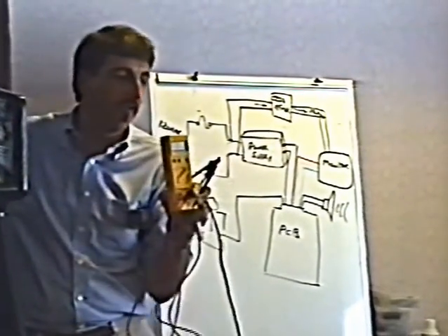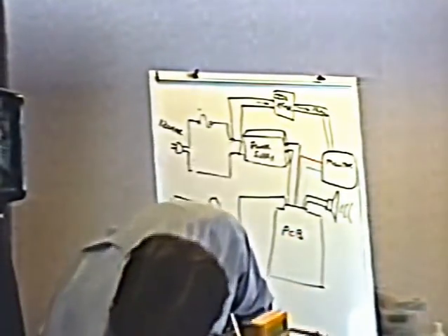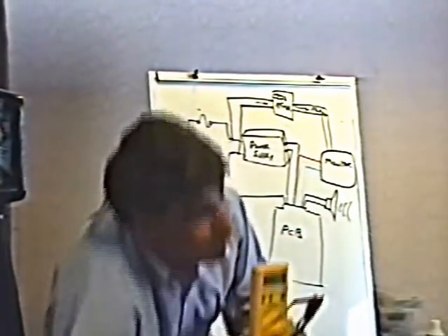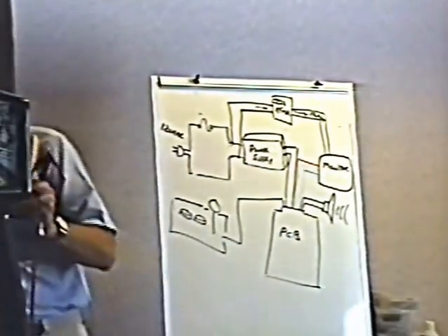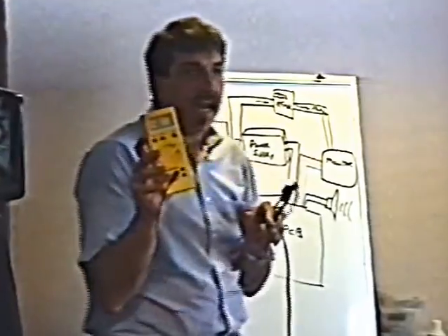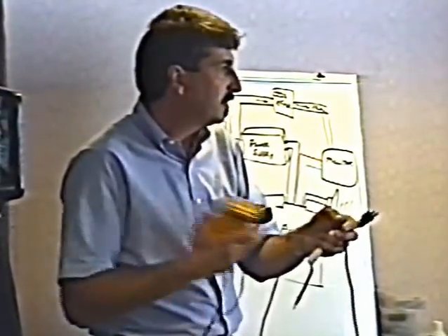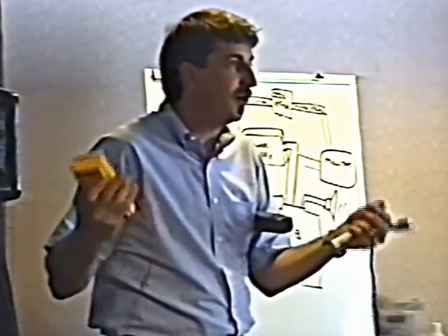Make sure all the switches are on. Are they on or off? There's an interlock switch in the front door here. Is that pulled out to turn it on? There's one in the back door. Are all the switches on? Yeah, they sure are, but I don't have any reading on this meter whatsoever, so I've got a broken wire somewhere. Something's broken: blown fuse, broken wire, something.